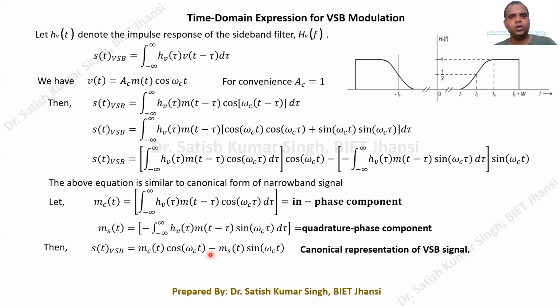If you think about the video signals, I have already explained that the video signal bandwidth is up to 4.5 megahertz, starting right from 0 hertz. So from 0 hertz to 4.5 megahertz, we have the spectral components. This video signal does not have any spectral null around the DC, and therefore it cannot be sent through SSBSC modulation. We cannot go for single sideband suppressed carrier modulation, because it does not have any spectral null around the DC.